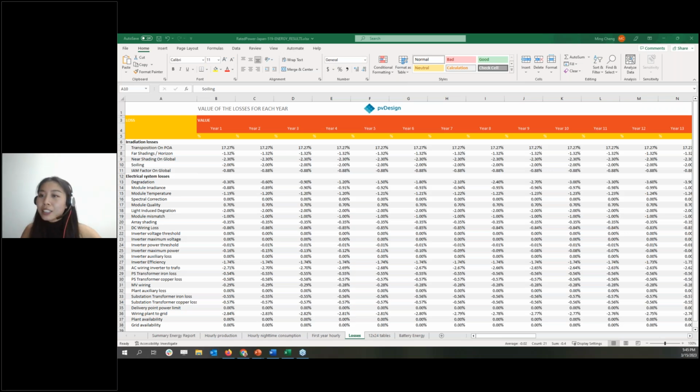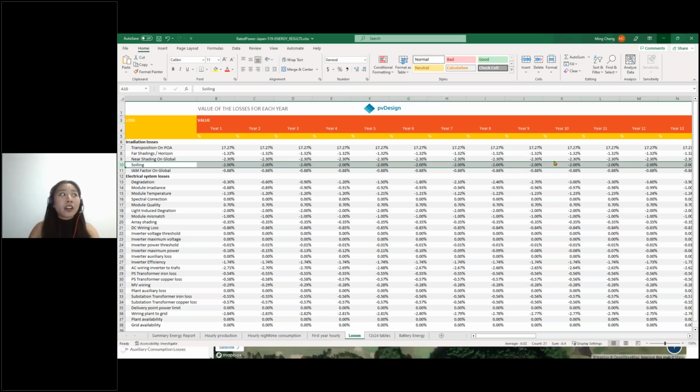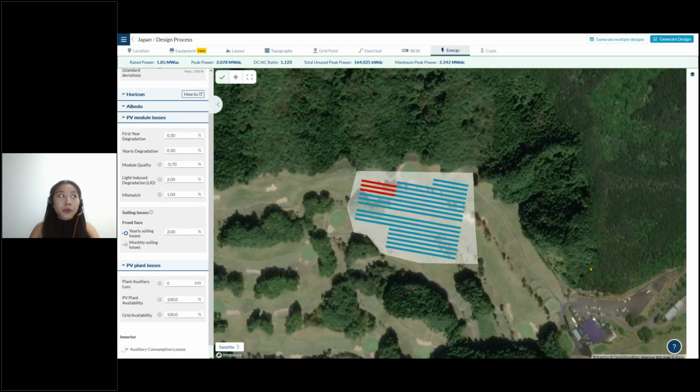From the explanation, is it correct to say the optimum azimuth depends on the horizon? Well, the azimuth depends on a lot of factors, for example, your terrain. If it's a very sloped area, then it is the prevalent dominant factor. But in this case, it is true that by varying the azimuth, we can avoid the far shading or the mountain shading.